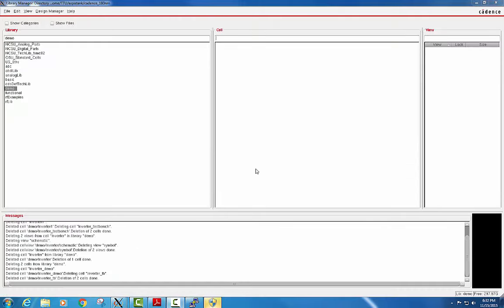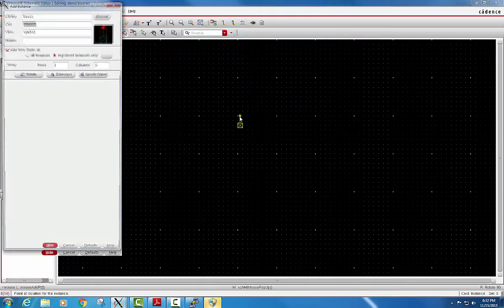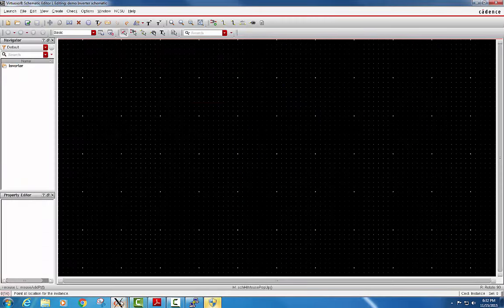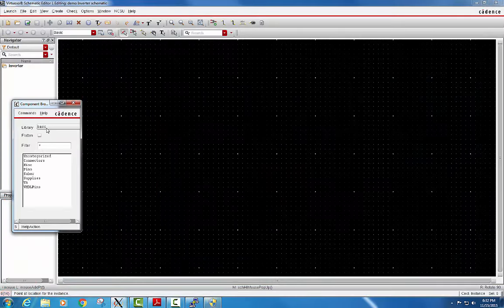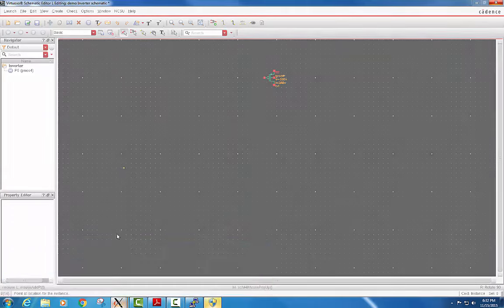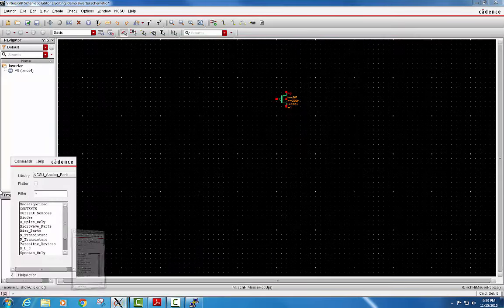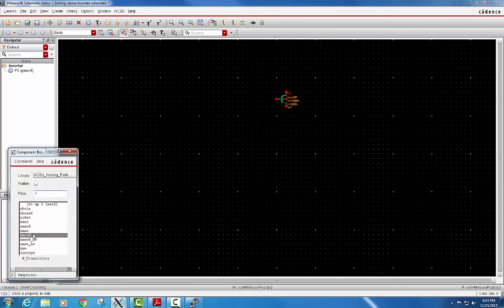This is the stage where we are going to implement a layout, and to implement a layout, let's create one schematic for the CMOS inverter very quickly. Let the name be inverter, and just follow all the basic steps. Select your P transistor, select your N transistor, and select NMOS in the similar way. Select NMOS 4,